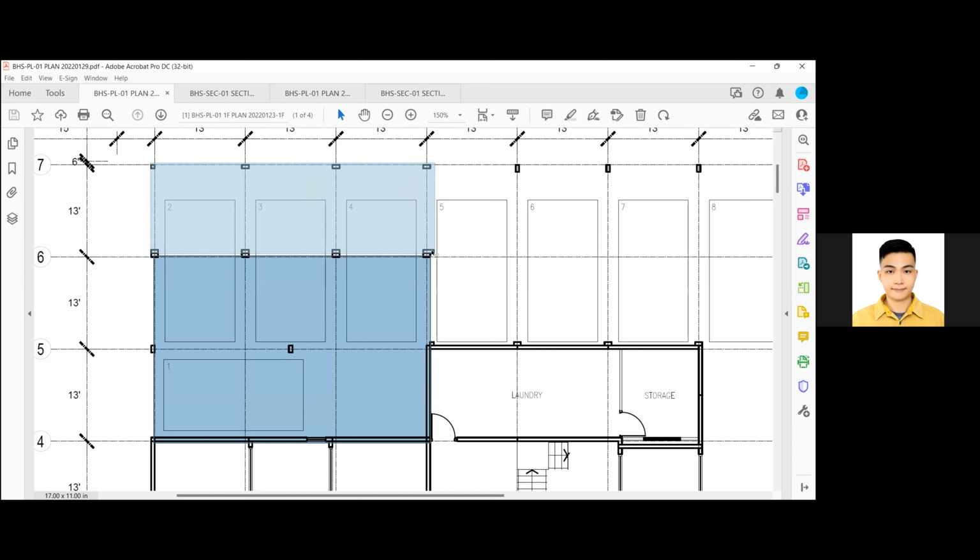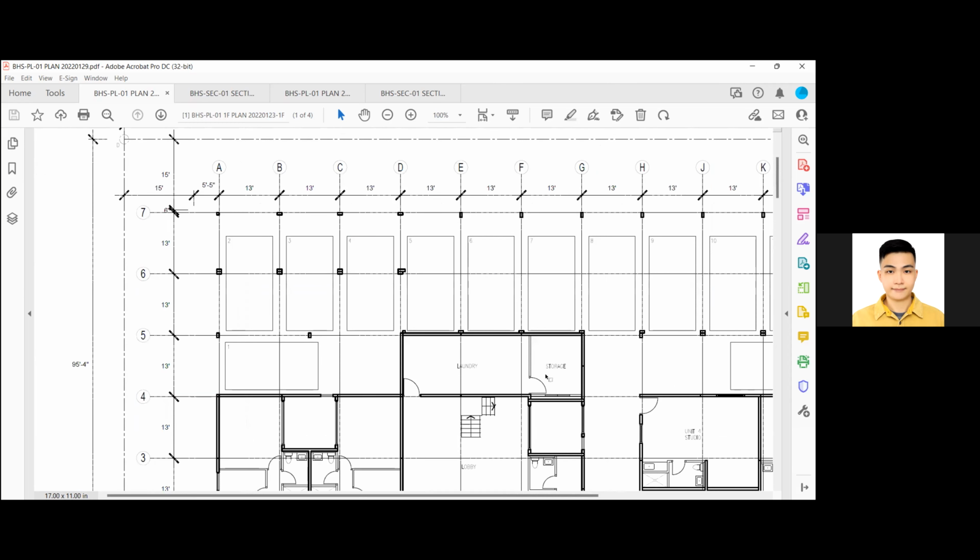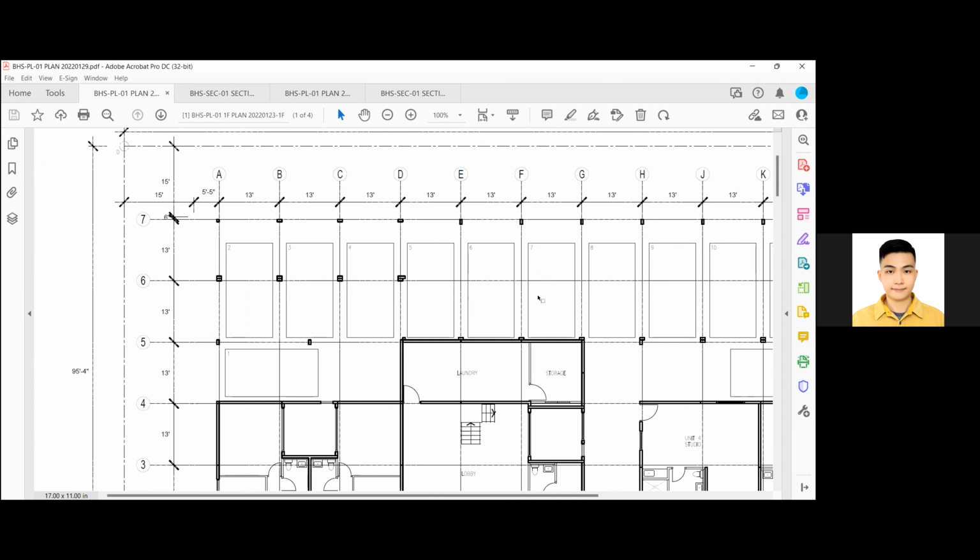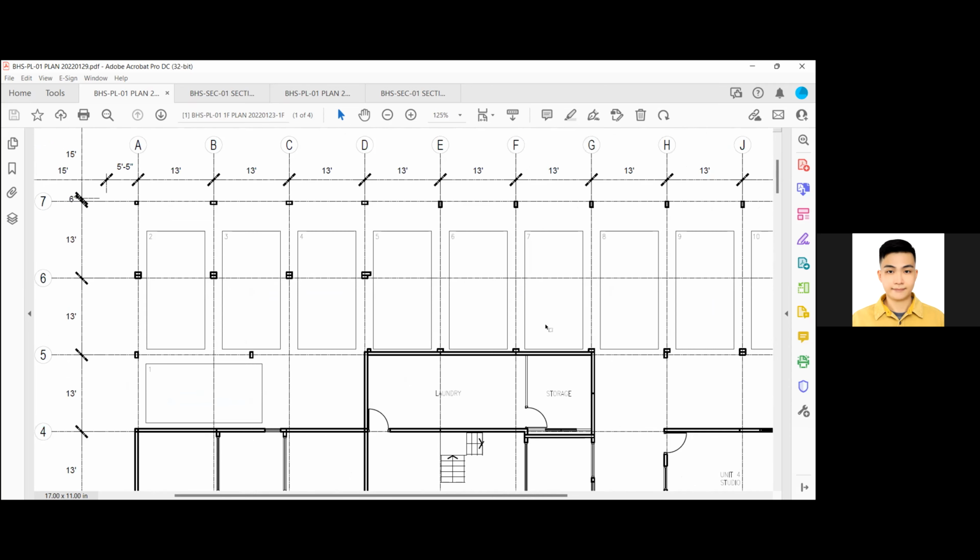For this case, we can somehow isolate the structural systems between the two, to avoid a more complicated interface between the steel systems and the wooden panel or floor slab structure. So here, the spacing still falls in an acceptable range.